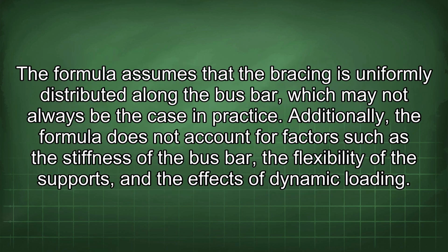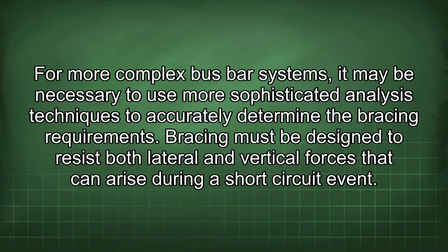The formula assumes that the bracing is uniformly distributed along the bus bar, which may not always be the case in practice. Additionally, the formula does not account for factors such as the stiffness of the bus bar, the flexibility of the supports, and the effects of dynamic loading. For more complex bus bar systems, it may be necessary to use more sophisticated analysis techniques to accurately determine the bracing requirements.